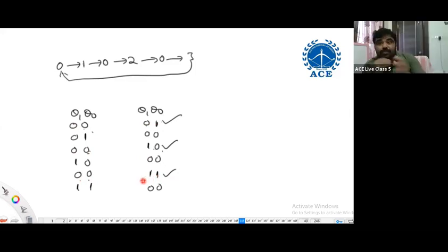All are correct. Can I specify multiple next states for one present state? Not possible. I can specify one present state, one next state. But you know, it is first time, second time, third time, because you are counting internally in your mind. That should be counted externally. Our system must be in a position to differentiate. These are not same. Then what should I do? I use extra bits to differentiate these.